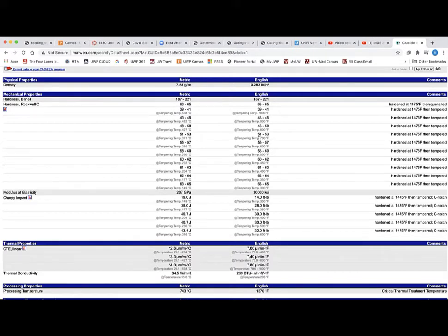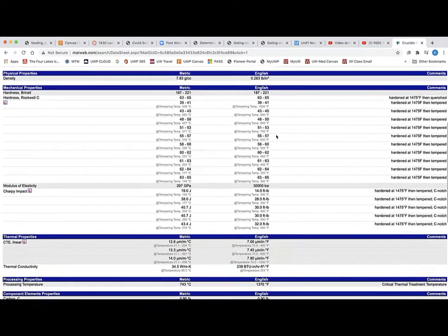is what we're doing actually, in our screwdriver, right? So this is the alloy we're using for a screwdriver. You're putting it in the furnace, you're quenching it, and then it's probably 63 to 65 hardness when you quenched it, very brittle. And then we temper it at 700 degrees for an hour. And so it'll be probably around 52 Rockwell C hardness.